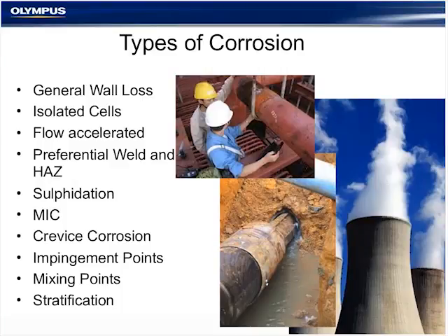However, you can also find instances of corrosion where you'll find isolated cells. And this is more common where, for instance, water might separate from a process fluid, and that water might pool in a particular spot, and that would result in concentrated or uneven corrosion in a specific area. Similarly, flow-accelerated type corrosion, where the product itself is abrasive. It essentially acts as sandpaper and is sanding the pipe from the inside out, and you're often going to find these isolated type corrosion, especially where there's some sort of focal point or some sort of bend in a pipe, something like that.